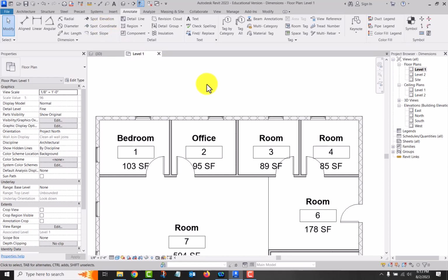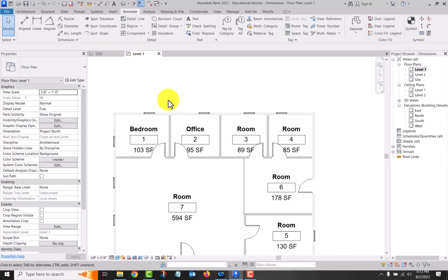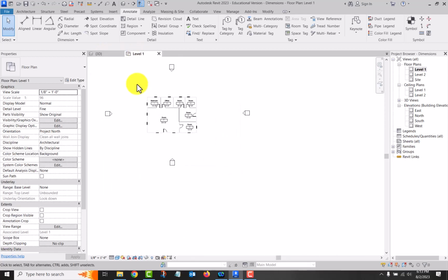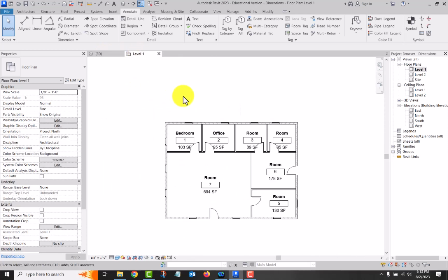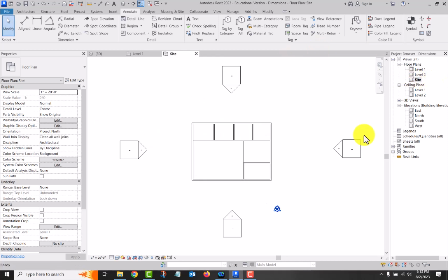And let's see, is it visible here? Nope. In the templates that we're using, those base points are turned off. Okay, but if we go to the site plan, let's see. There we go. These are the project base point and the survey base point. So as far as a project goes, that's our origin. That's our 0 point, and everything else is based on that.